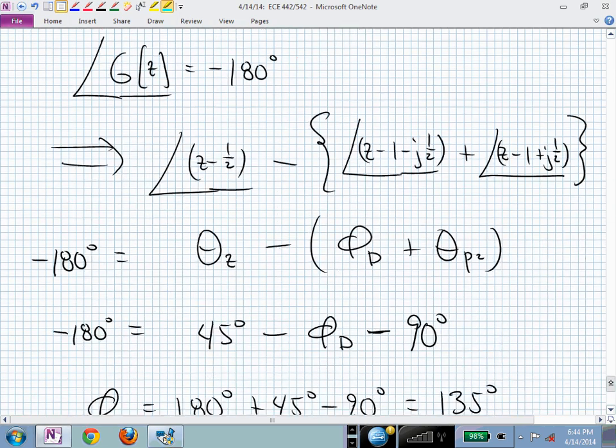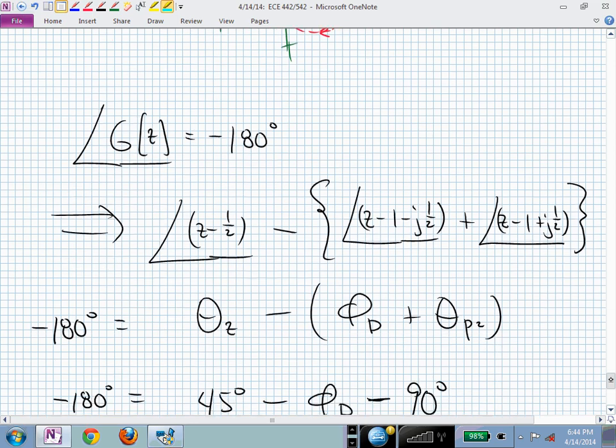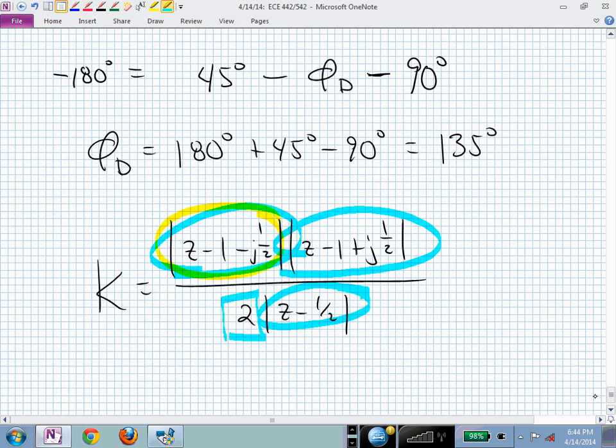If you now looked at what values of K, well, you already know where the re-entry is, but if you didn't know, you would start evaluating this K formula at, let's say, z equals 0 to maybe z equals minus 2, and say, is there a relative minimum in that region?